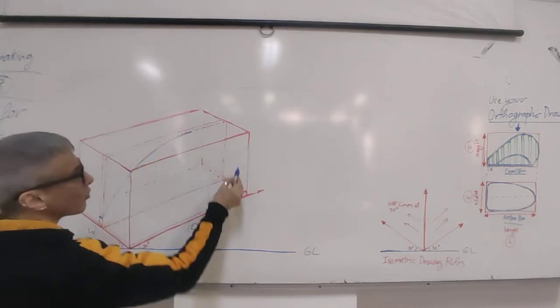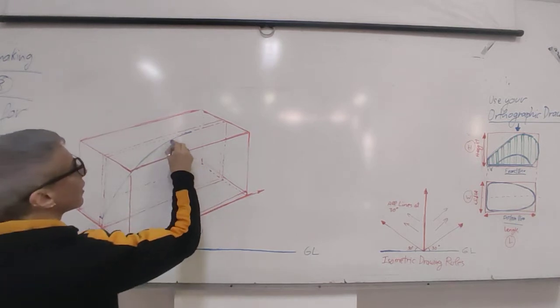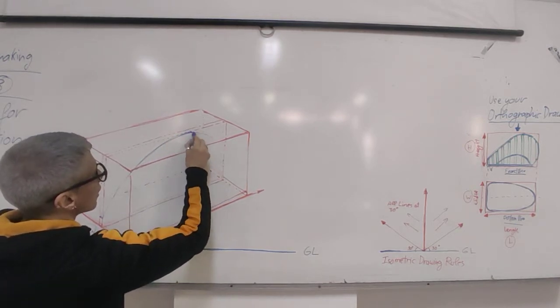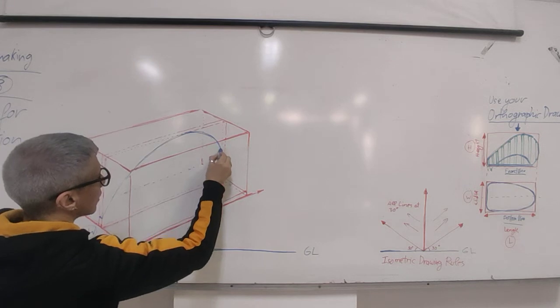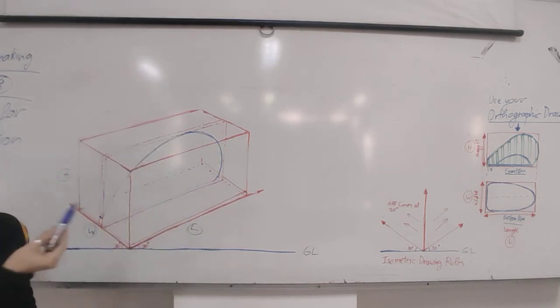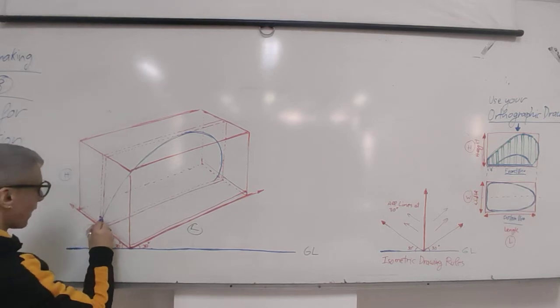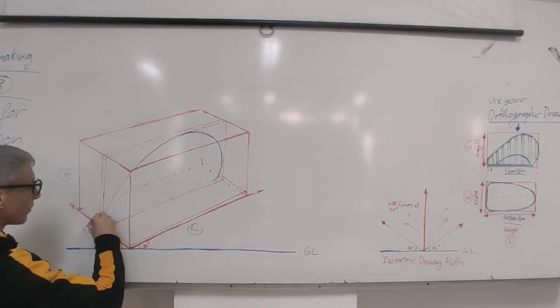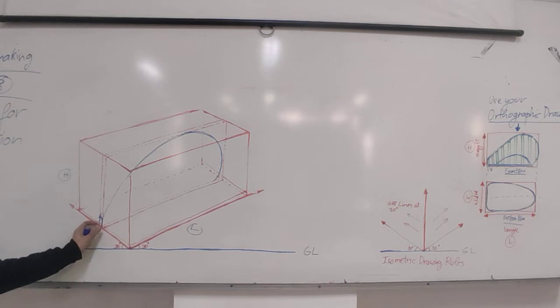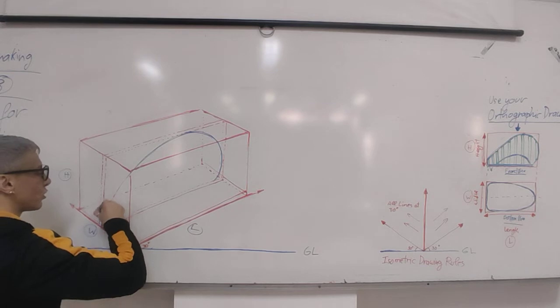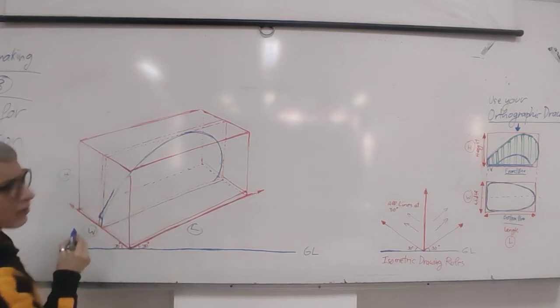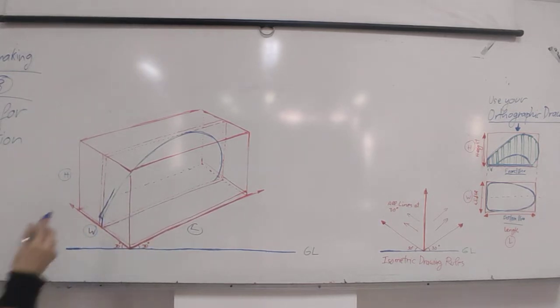So after this point, for example, the mouse starts going backwards into some kind of a curve. It's roughly just an example, okay? But each one of your mouses will be totally different. This is just to understand the steps and the technique, how to approach. Okay. So here we have this. And because we have 2 millimeter thickness, we will draw the view twice, okay? So we will draw the view in 2 millimeter thickness. Let me first see how it looks. Okay, it works.